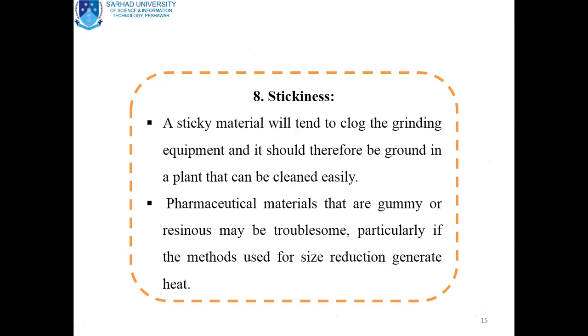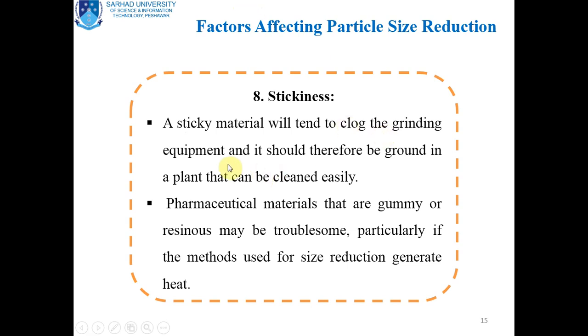Stickiness is also one of the factors affecting particle size reduction. A sticky material will tend to clog the grinding equipment, and it should therefore be ground in a plant that can be cleaned easily, in order to prevent clogging of the grinding equipment or mill. Pharmaceutical materials that are gummy or poisonous in nature may be troublesome, particularly if the method used for particle size reduction generates heat.